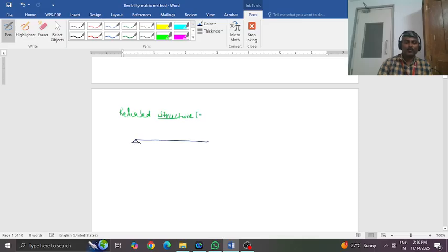So here you have removed MA, so you got a simple support there, and you broke the beam here, so you got another simple support here. So now you take only the loads. Your job is to formulate delta L. So take only the loads.